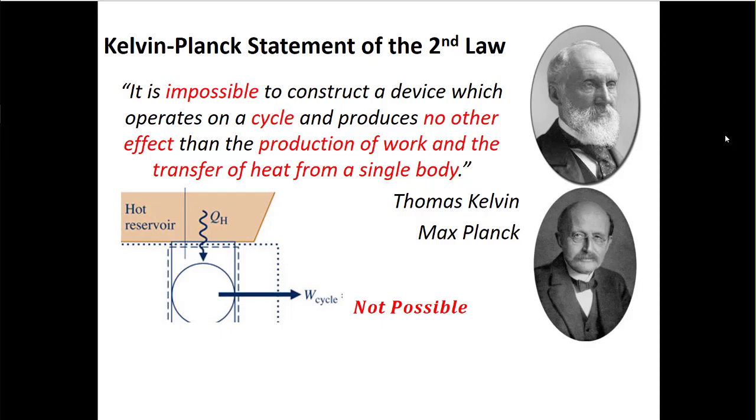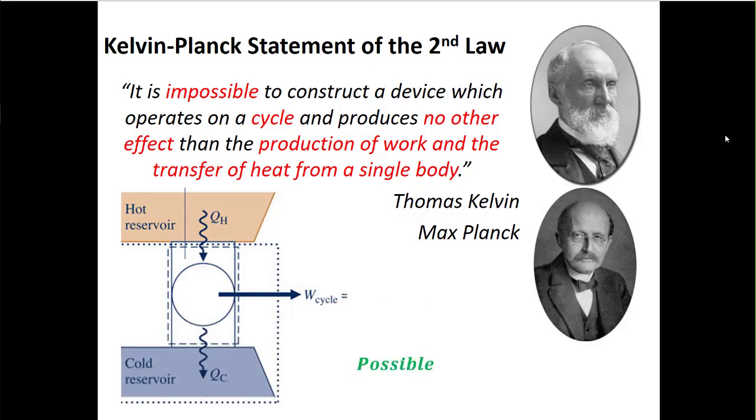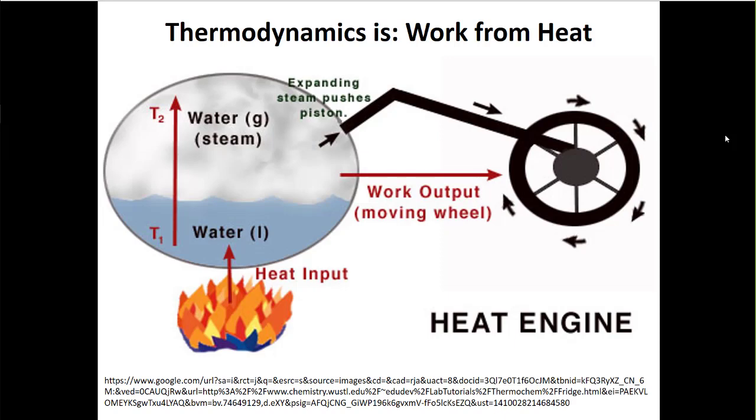Because first, when we talked about the second law, we talked about it in terms of the equation, right? But then we talked about it conceptually, and Kelvin and Planck were talking to us about heat engines, right? And they said, yeah, you can make a heat engine that takes heat in and turns it into work, but you can't turn all the heat into work because you have to have some kind of a heat sink. You have to keep your engine cool, right? So that means you can't turn all the incoming heat into work, right?